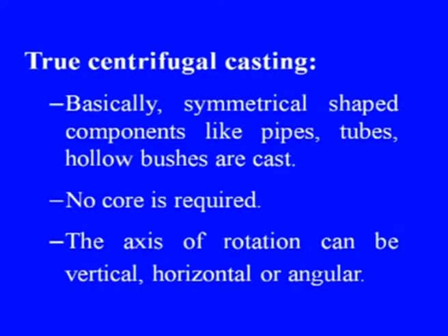Through centrifugal casting, basically, symmetrical shaped components like pipes, tubes, and hollow bushes are cast. In these products, no core is required. The axis of rotation can be vertical, horizontal or angular.